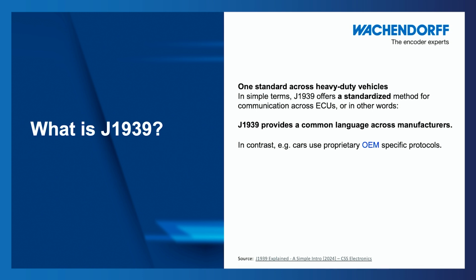As an example, one thing you'll find with J1939 is there's a lot of standardized data, a lot of what they call PGNs, which I think we'll talk a little bit more about later, that are standardized across multiple manufacturers. However, there's a lot of proprietary information that's only accessible if you happen to know the PGN location, and not all manufacturers share that data. So again, it's a mixture of standardized data accessible from standard addresses, if you will, along with some proprietary stuff that I think a lot of manufacturers try and hide a little bit.